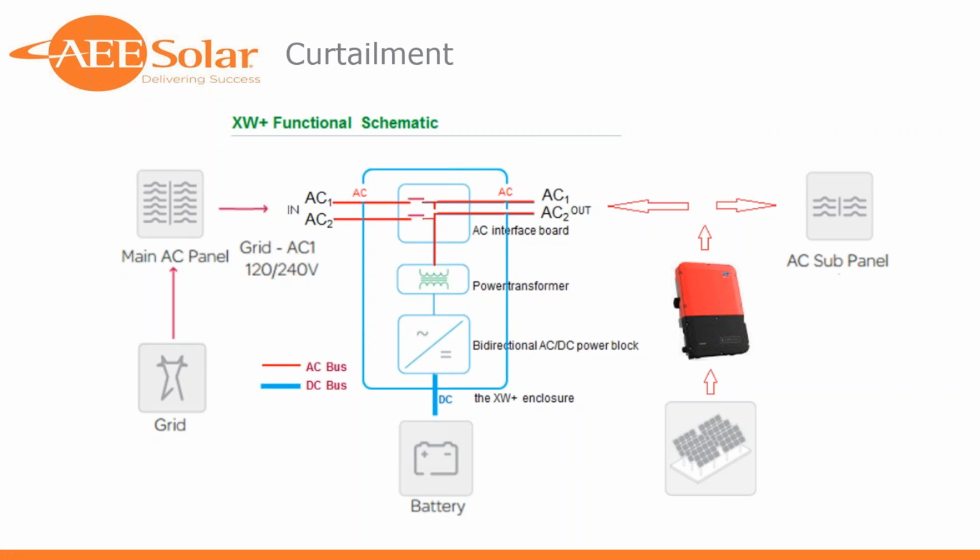I'm going to do my 5-minute count up, make sure that the grid remains qualified, and then I'm going to inject as much current as possible that I can harvest from the array. And engineers being what they are, they've gotten really efficient devices that harvest a ton of power and will inject as much current as they can without exceeding their ratings or tripping circuit breakers. So that's the goal in life of a PV inverter.